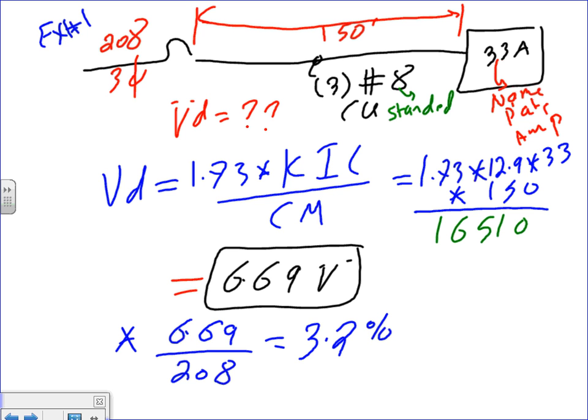That's one way to go about it. Say it again: 3% of 208 is 6.9? We came in at 6.69. Multiply 208 times 0.03, not divided. What's 3% of 208? 6.24. So our voltage drop is greater than that. So this is ugly. This is bad.